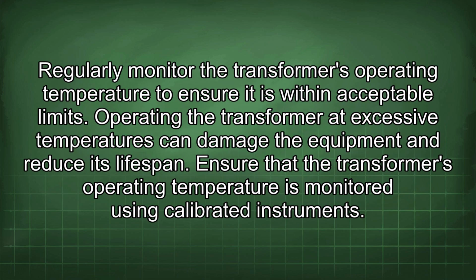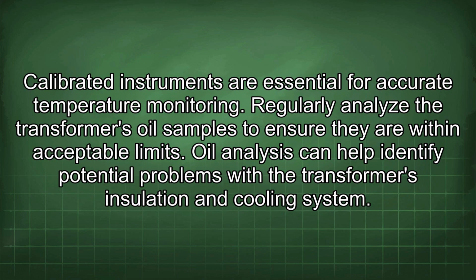Regularly monitor the transformer's operating temperature to ensure it is within acceptable limits. Operating the transformer at excessive temperatures can damage the equipment and reduce its lifespan. Ensure that the transformer's operating temperature is monitored using calibrated instruments. Calibrated instruments are essential for accurate temperature monitoring.